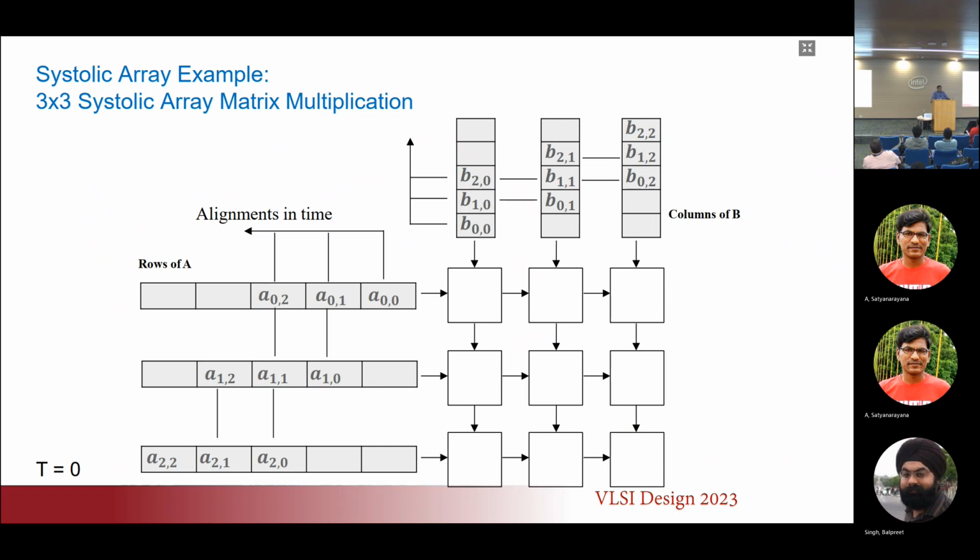The cost is tremendous, right? Because you got 64,000 multipliers and adders working in parallel. You could do 64,000 only because it is 8-bit integer. You could not do 64,000 if it was all 16-bit floating point. That power would be unsustainable, right?